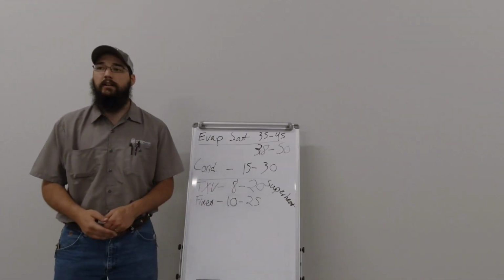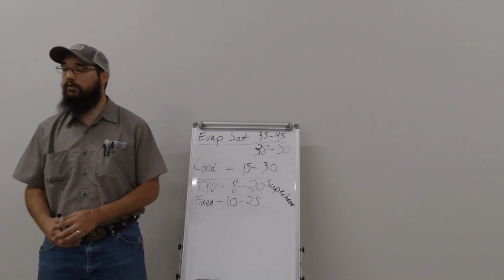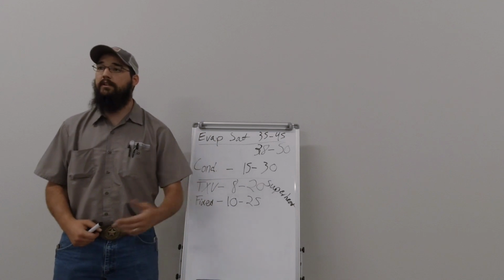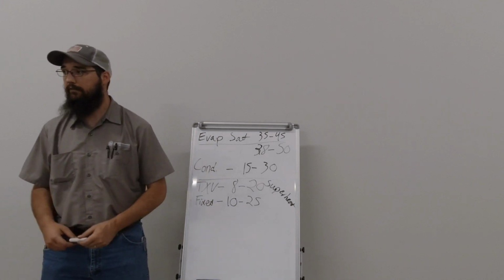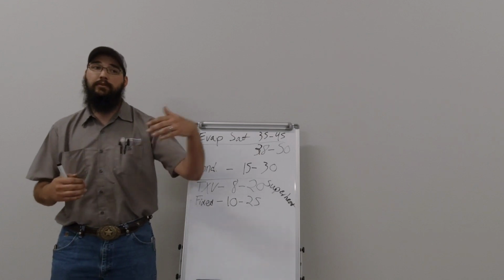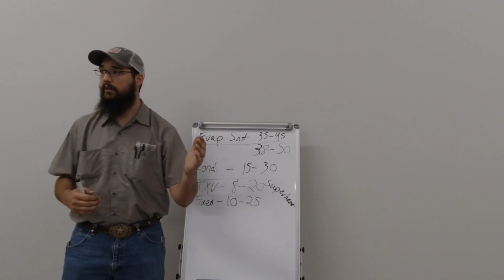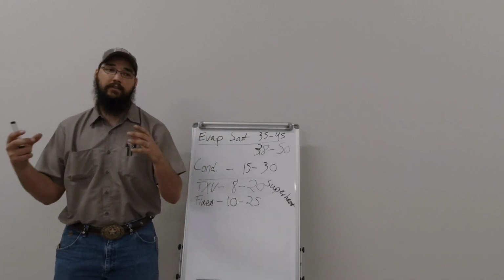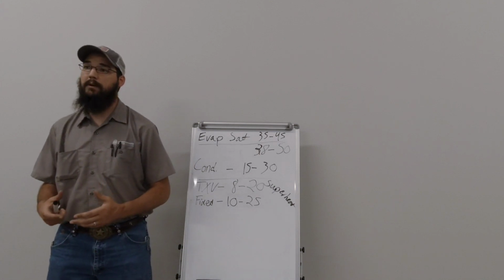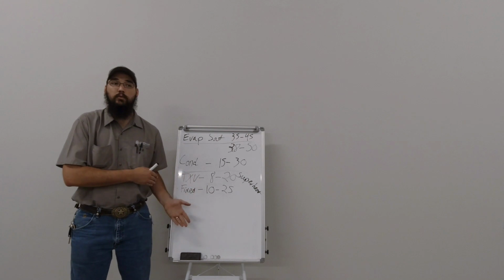When they're not set correctly, they're either set too low, so you start getting occasional flood back to the compressor, and the compressor is now having to deal with that. The oils and the bearings are having to deal with that, which is really hard on them, even if you don't send it through the compressor itself. Right? It never makes it that far. Just the fact that it was allowed to touch the oil starts to mess things up. That's saying that your superheat was too low.